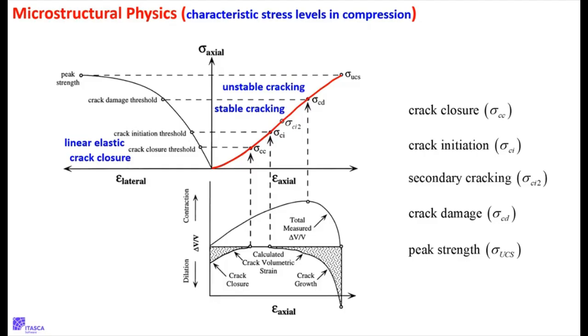So the result is you've got to really understand what's going to happen to an excavation, because that's where you're going to put the nuclear waste. So there's all this research that was done on Lac du Bonnet granite. It's probably the most studied rock that I'm aware of. They did a huge amount of complicated testing so they could get this stuff here. Because this is not just standard rock mechanics, building an excavation that has to last for 10 or 20 years. For this excavation for nuclear waste, we've got to say what's going to happen over 100,000 years. Is it going to just sit there? Maybe there's some kind of time-dependent processes going on. So to study that,